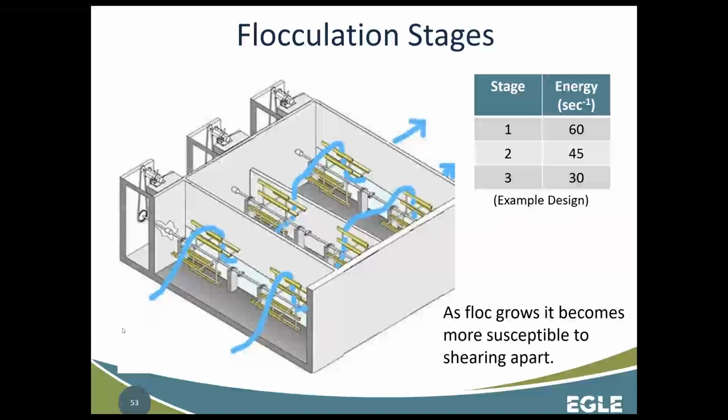So if you've got a bunch of flow coming directly into the middle of this basin and you didn't have any baffles, a lot of it would just go straight through the center and you'd end up with sort of dead zones on the sides. These baffle walls are going to help with that.